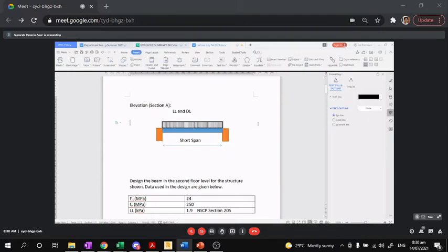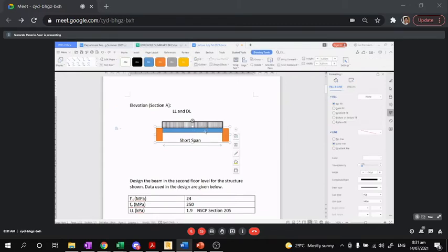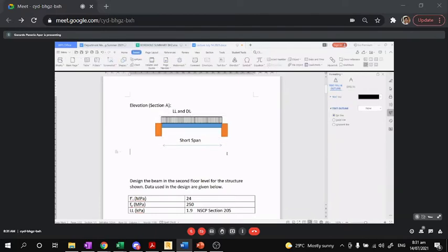Okay. So, this is what we call the live load or dead load. I have included it in the group. So, that is my symbol for the dead load and live load. Now, the live load is the people on the floor. Usually, you get it from the code, the building code. If it is residential, it has a particular magnitude, or if it is an office building, or used for whatever. So, you just consult the National Structural Code of the Philippines. Okay? And why is there a dead load? Of course, because the slab has weight. No?